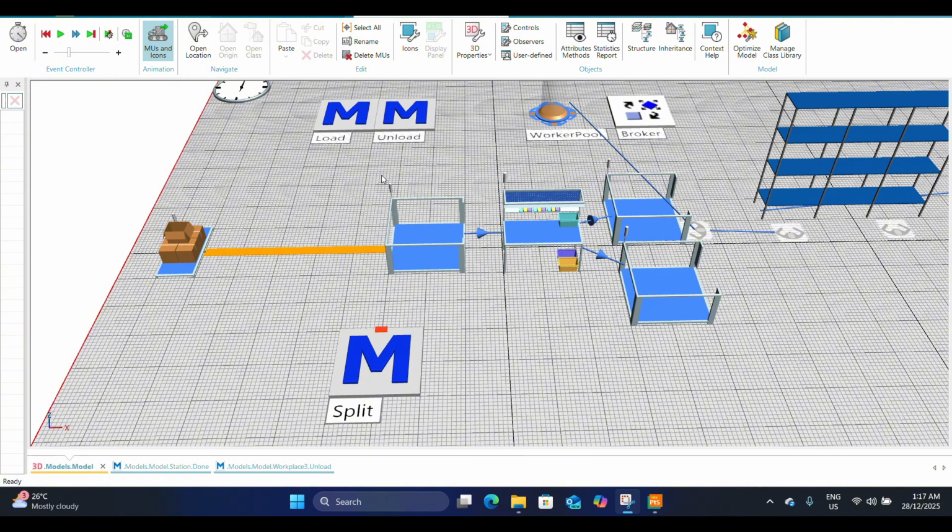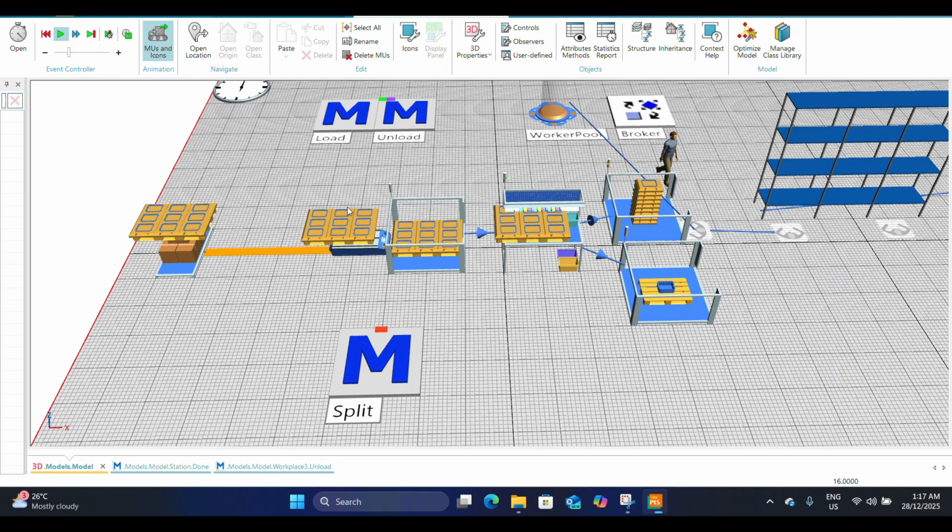First of all, the source here means that the lorry unloads the components in bulk on a pallet at the warehouse. Therefore, the AGV, in place of a forklift, will transfer the pallet to the buffer, and the buffer represents a temporary storage awaiting detachment into the box.